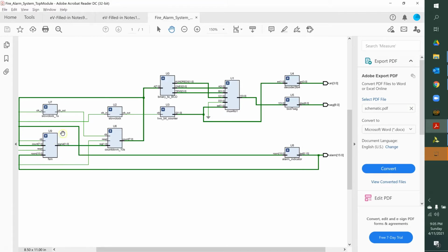And then the main part, the finite state machine, FSM, this was right here. This is basically responsible for making sure the countdown goes down by 1. That signal is triggered, and only then it starts counting down. It is also taking the inputs as room, and then we have the count here, which is basically the input.